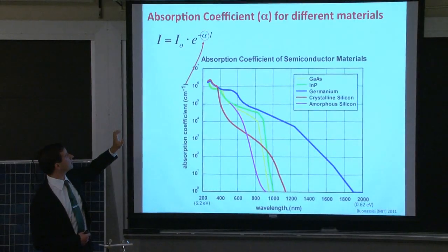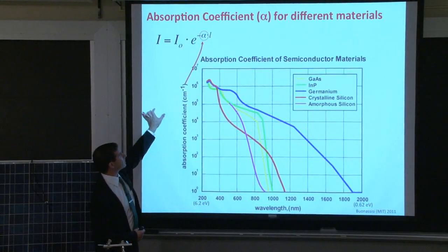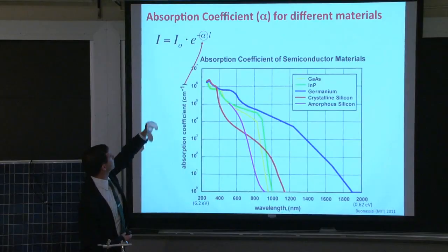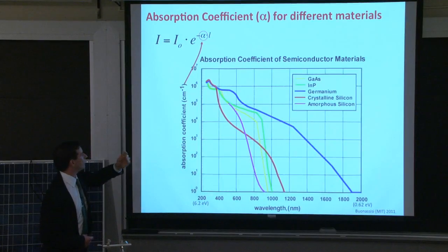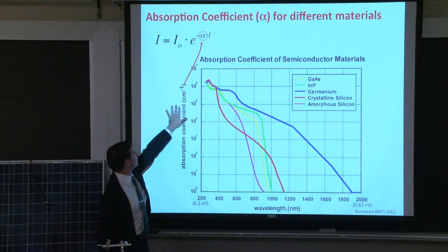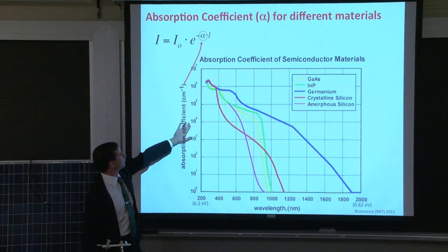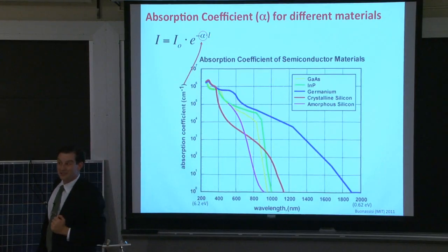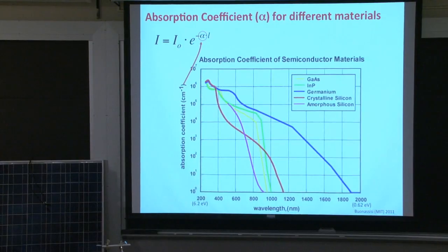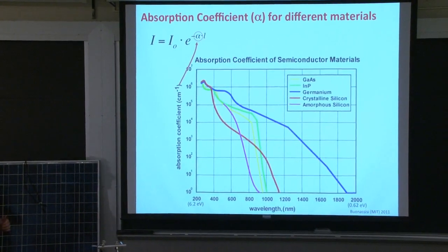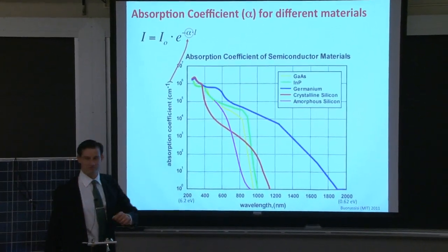Then we would take the log of both sides, typically, right? And solve for our L based on the alphas that we have here. Again, units of alpha would be in inverse centimeters, and so the L's that you obtained, let's go for gallium arsenide first. Did anybody manage to walk all the way through that calculation?